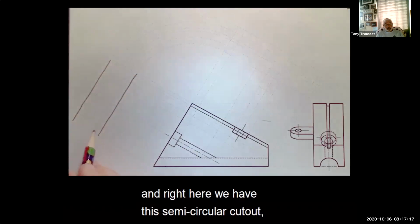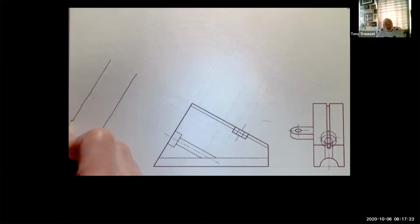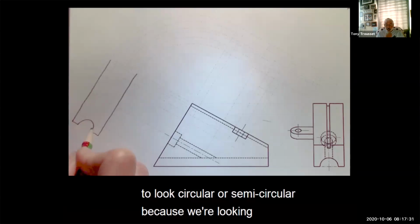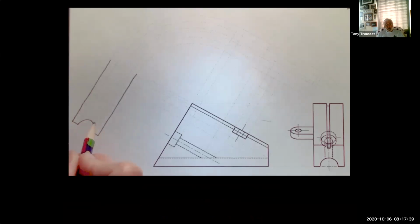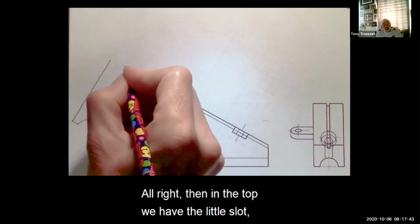And right here we have this semicircular cutout. So we need to put that in. Now this cutout in the auxiliary view is not going to look circular or semicircular because we're looking at it at an angle. So it's going to be elongated a little bit, but the projectors will tell us by how much. All right, and then in the top, we have the little slot